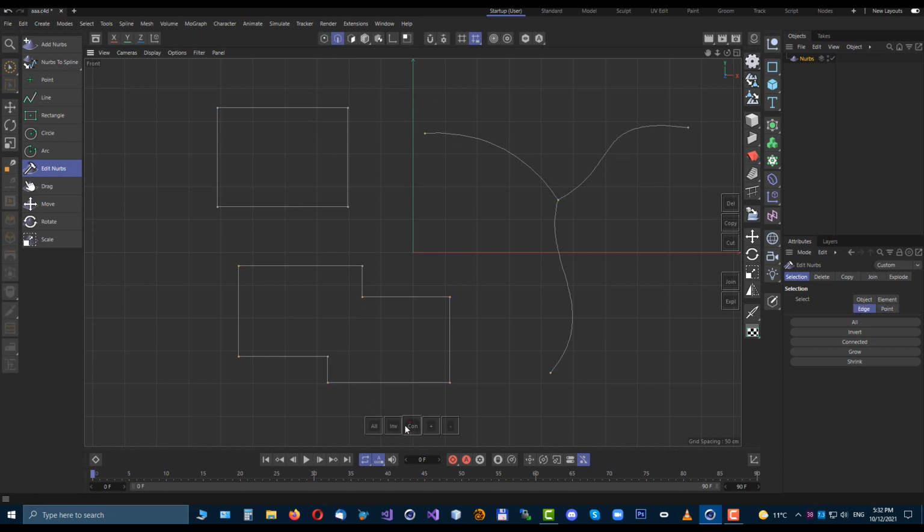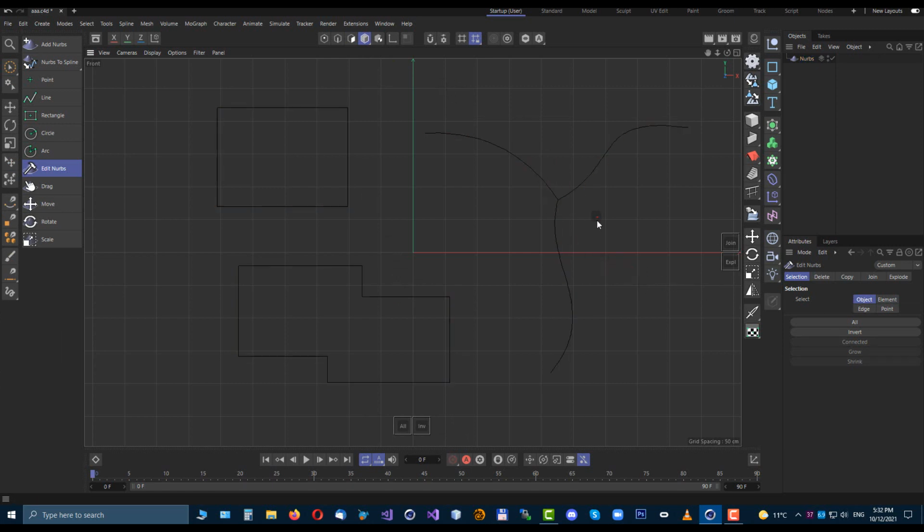The Nurbs selection system is connected directly to the Cinema selection mode, so you can change selection also here with the Cinema selection switch. In point mode, you can select all points. In edge mode, you select edges of curves or segments of curves. Now only curves. When Nurbs surfaces arrive, it will also be edges of Nurbs surfaces. With polygons, Cinema polygons selection, you are selecting elements of the Nurbs object. So again, in this case, it is just curves. So element selection means now curve selection, and object selection is the same as in Cinema. So the whole object is selected, or more object selection.